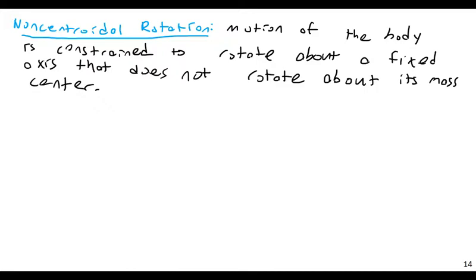But when you design a large flywheel, one of your primary problems in terms of manufacturing is balance. If you're designing a flywheel to rotate at thousands of RPM with tremendous amounts of energy, a huge mass spinning very, very fast, and it is not almost perfectly balanced, it is going to shake itself to pieces. It will destroy itself by its own rotation. So this is something you actually want to avoid when designing rotating machinery. But anyway,